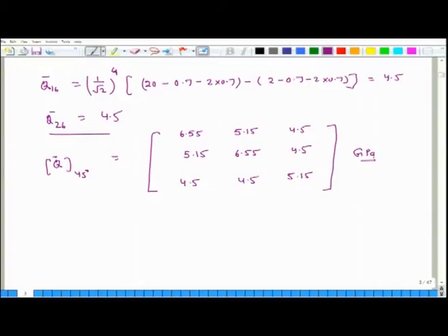So, that is my Q bar matrix for the 45 degree layer, and then we have another one for the 0 degree layer. So, next we start computing the A, B and D matrices. The ij-th element of the A matrix is the sum from k equal to 1 to n, and we had discussed this earlier, of Q bar ij for the k-th layer times the thickness of the k-th layer.